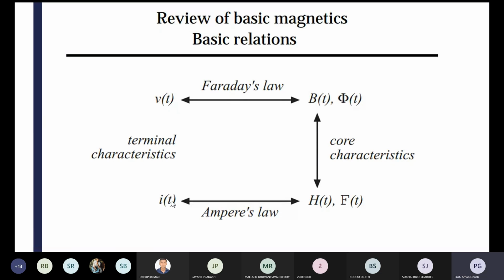If you increase the strength of the current, how will it be magnetized? In the ferromagnetic core there are a lot of polar magnets, which initially are not aligned. If you give some external magnetic field, the polar magnets are aligned in the orientation of the lines of force. How do you increase the strength of the magnetic field? With NI: you can increase the number of turns, or you can increase the current intensity.